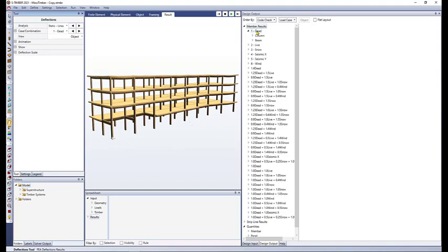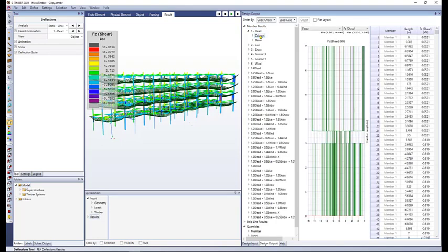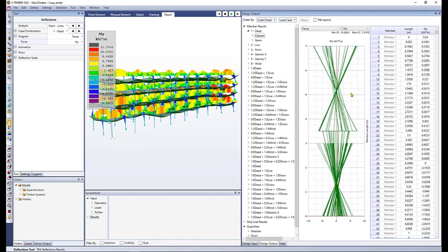Let's say, for example, you're interested in the dead load results, maybe for the columns. I just click in the columns tab, and you can see in this case it is the F-set shear force. You can see it graphically. Here are all the results in spreadsheet format, and the selection also gets highlighted here. And you can choose another type of force, like moments in Y, and it will show for each one of these columns here and here.